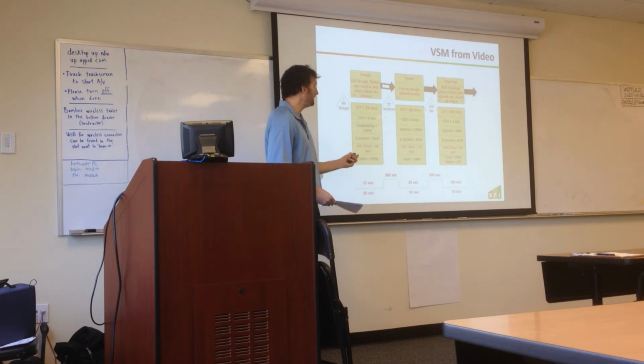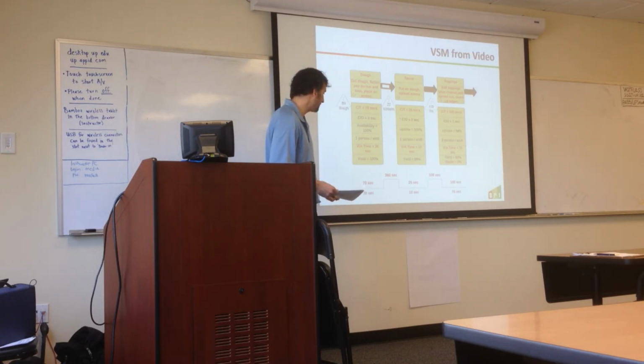Okay, so that would be data we would record, and that would go down here in the bottom: 73 seconds, 25 seconds, 100 seconds. What I did also was I broke out and figured out how much of that time looked like value-added time. And I came up with 70 seconds, 10 seconds, and 30 seconds. The rest of that I felt was wasted effort and motion. That could be an opportunity to reduce it down further. So that's what I recorded in here as well.